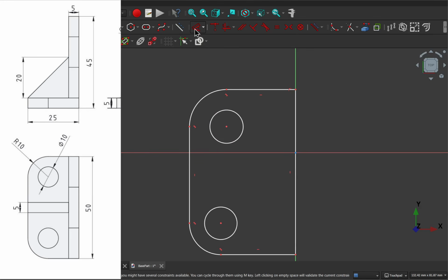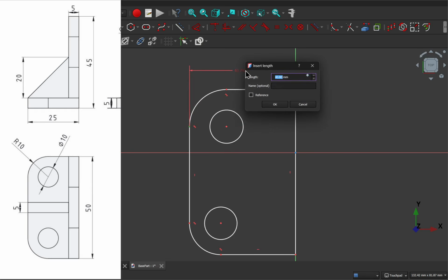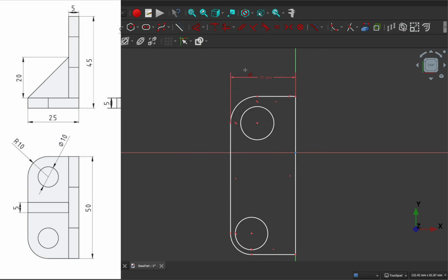So I'm going to select the dimensioning tool and select this point. When we do that, it dimensions to the center of origin. So if we come up and select the other point, this one here, it will now dimension this length. We come up and just drop it into place, and we'll set that 25 millimeters. Everything will adjust, and we do the same on this point, down and click on this point, bring this out, drop it, and set this one 50 millimeters and hit enter.